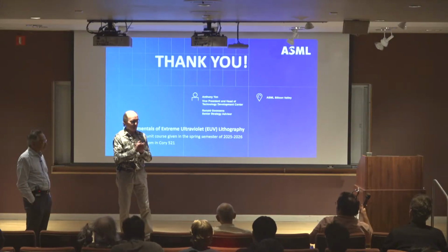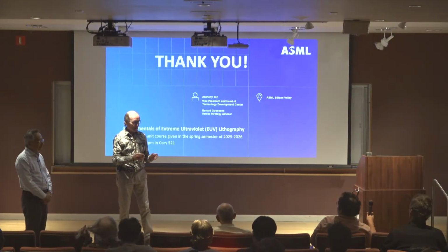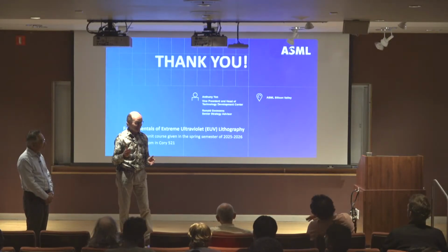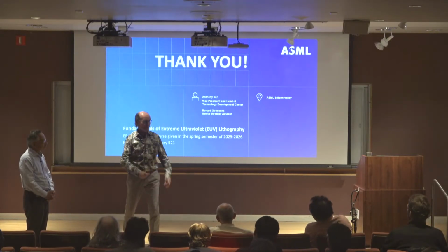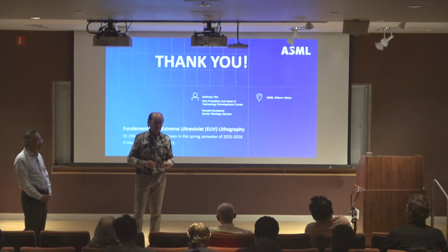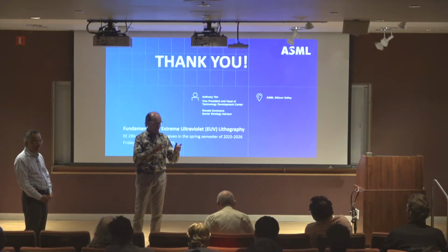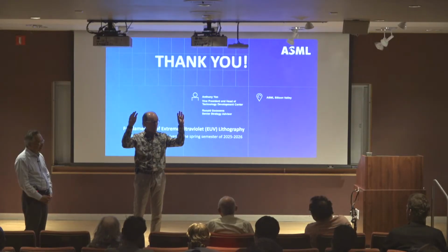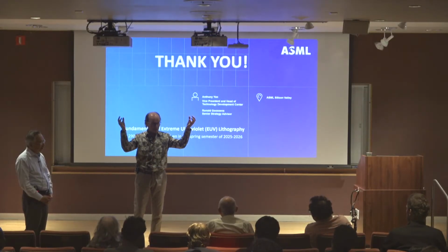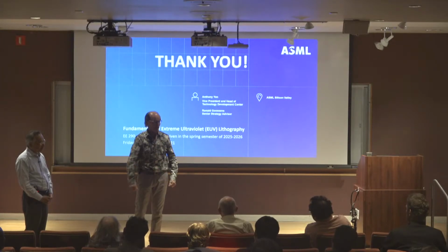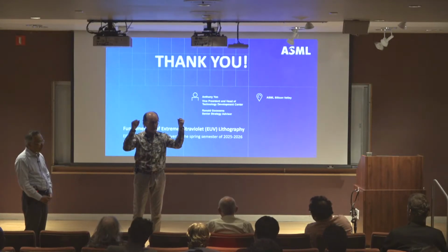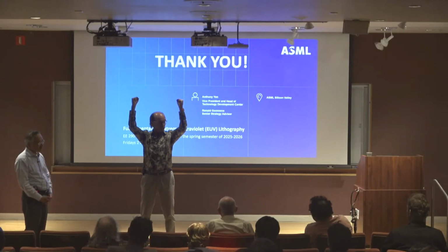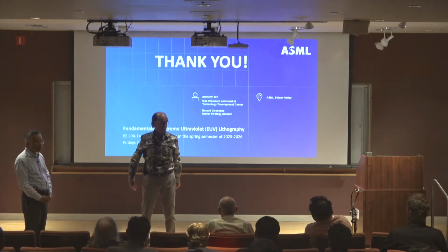Okay, so let's define first what the end user is, right? If the end user is Apple, then they tell TSMC it's your problem, right? TSMC will tell us, hey, we want to use dipole illumination because that gives the very best contrast for one-dimensional patterns. Can you make a light source where all of the light only comes from these 2 points in that whole disk?